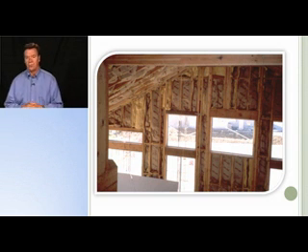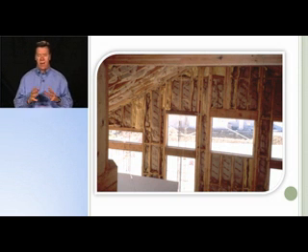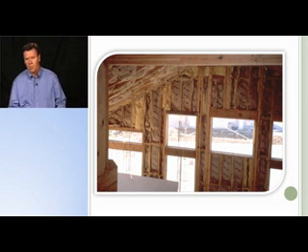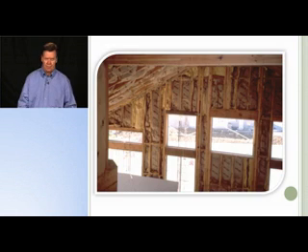Same thing happens with walls. You can see here the insulation is just crammed in between the studs instead of actually being cut and fitted into that opening. Again, these compressions have a big impact on the overall performance. It can reduce the performance anywhere between 30 and 50%.